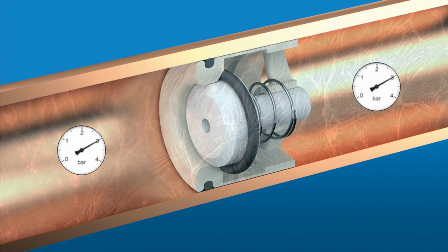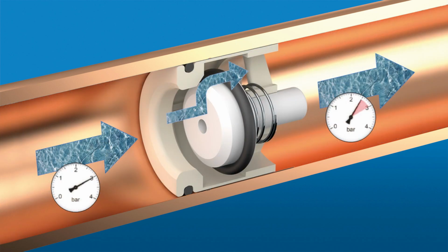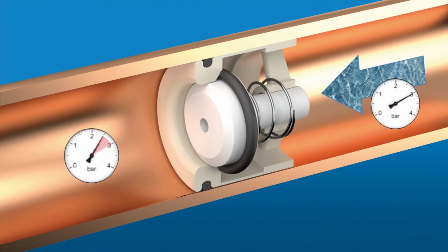As you know, a non-return valve is a mechanism which opens and closes to let water flow in one direction and not the other. So typically, non-return valves are used to prevent hot water flowing back into the cold water supply or vice versa. This cross flow is very dangerous because warm water can create the ideal conditions for bacteria to proliferate. But during their lifetime, non-return valves may fail because of scale build-up or impurities. That's why non-return valves must be checked at least once a year.